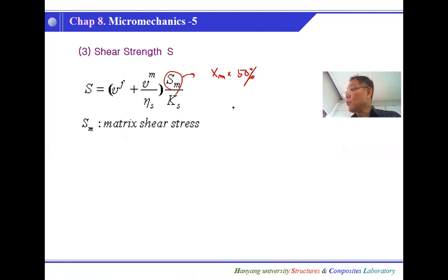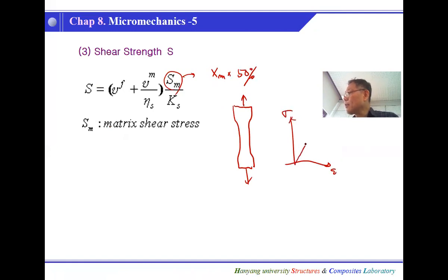Well, we can use a dog-bone type test to measure the resin strength and the stress-strain curve. A typical stress-strain curve goes like this, and since it's a plastic, epoxy will just break here, and the thermoplastic will go like that, with a very high failure strain. But here is the stiffness, and here is the yield strength or ultimate strength. So I will call this one XM.